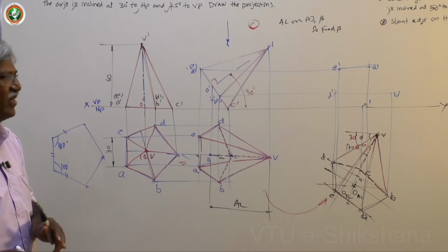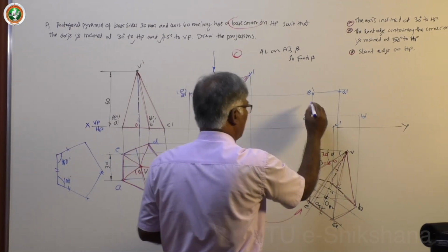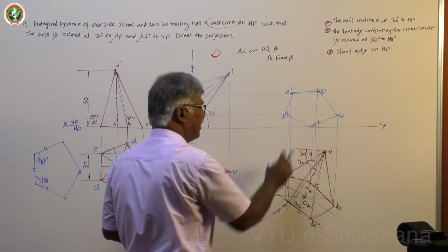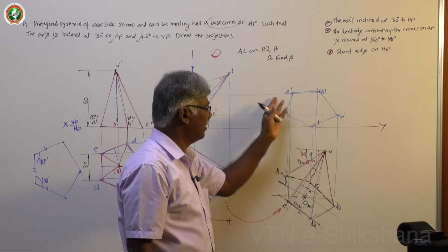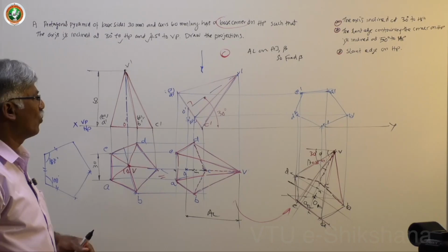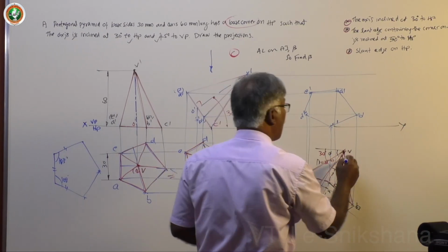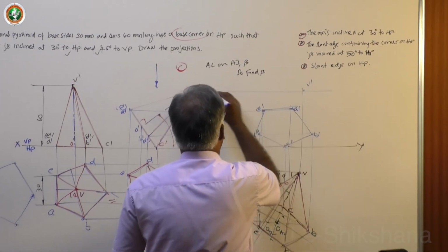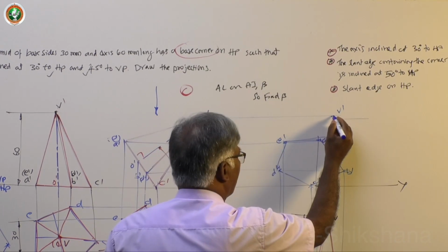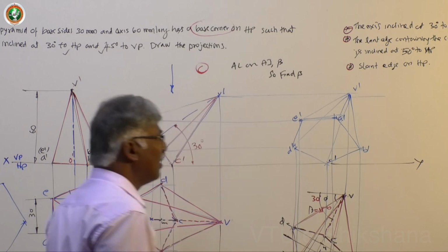Every time you check twice whether you have made it properly. Now before V, let me join this to avoid any confusion. You may get variations, D this side, E this side, because of angle changes. Here I have taken an approximate angle and am drawing. Now mark V. Now join all corners of the pentagonal base with the apex.